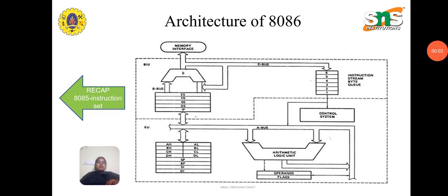Welcome to the lecture. In this lecture, we are going to discuss the 8086 microprocessor. The 8086 architecture is different from 8085, whereas the 8086 microprocessor is an enhanced version of the 8085 microprocessor that was designed by Intel in 1976. It is a 16-bit microprocessor having 20 address lines and 16 data lines that provides up to 1 megabyte of storage. It consists of a powerful instruction set which provides operations like multiplication and division easily.